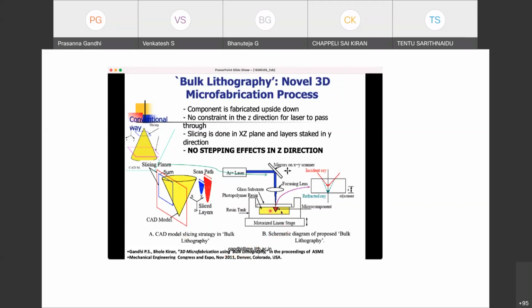So the idea here is, this is a photopolymer resin, and you take a laser beam and focus it at the resin and substrate interface. Okay, and then some structure starts coming up there. Then you scan the laser beam, and that structure will turn into a wall. As the laser beam is scanning, you change the intensity, and then you can shape the wall into whatever desired shape. The scan path is in this direction; you increase the intensity, you get a deeper formation. You decrease the intensity, you come back and get a smaller fabrication. So you can tune the intensity to get whatever free surface shape you want.